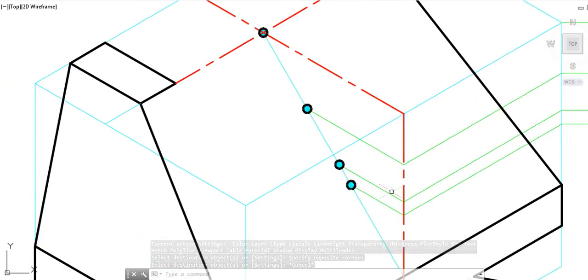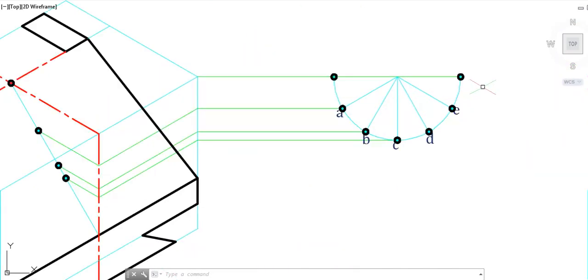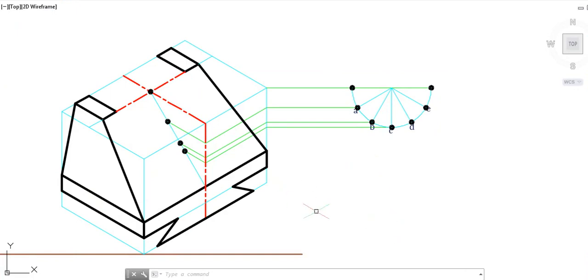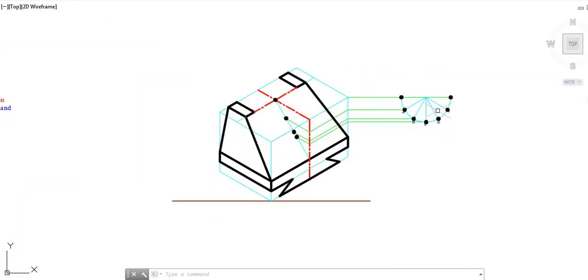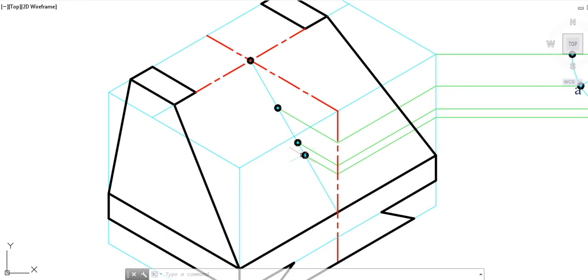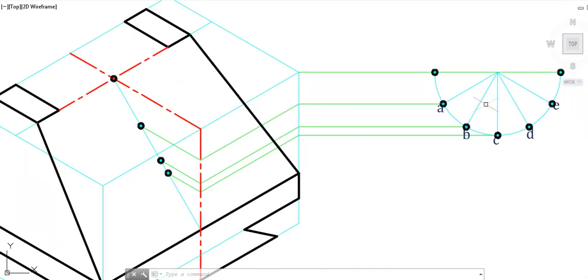Now one thing is very clear, that from these points the radial distances are emerging. We can see them here. This particular radial distance from center up to this point, and this similar radial. Now there will be the distance horizontal from here. See, the logic behind it is, when we are looking from this side for the front view, we will be able to see this circular point. So this distance of the point will remain the same no matter whether the point is present on this inclined surface or it is present on the backmost surface. So that's why we will go by this logic. So let me highlight those distances also for understanding.